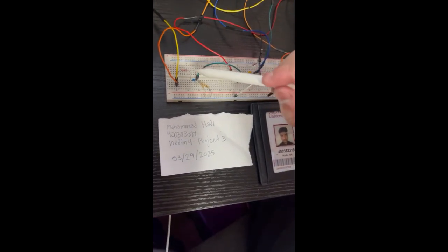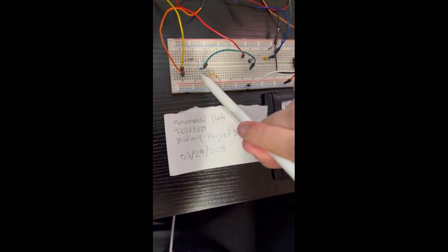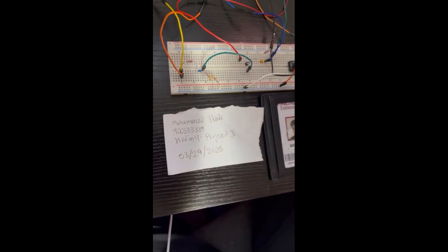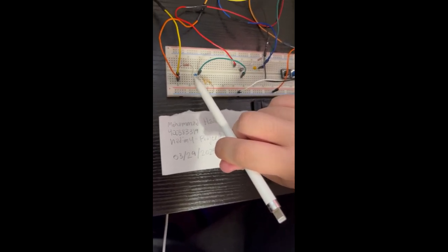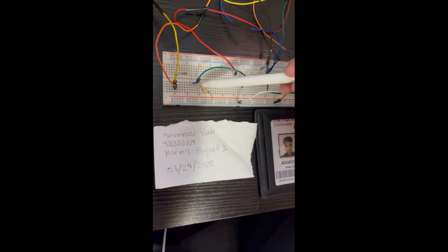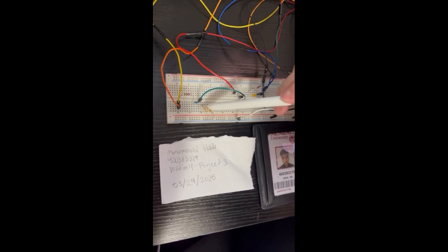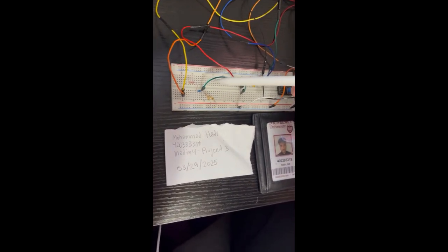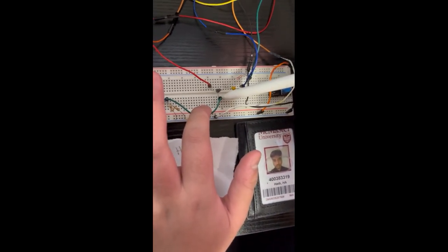It's connected to the 100 ohm resistor, which is also connected to this blue thing, the 100 nanofarad capacitor. It looks different because I got it from somewhere else, so it's not from campus. But yeah, it's this 100 ohm resistor connected to the 100 nanofarad capacitor, and in the same node are the two 10k resistors right here. The two resistors are, as you can see, both connected to ground in parallel. And also in the same node as the capacitor and the two 10k ohm resistors is this green wire, which you can see right here. It's connected to the base of the BJT, so that's the base.